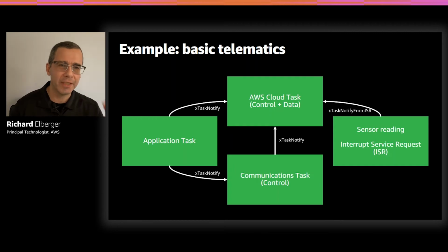But if I have an extra clock on the MCU, on the microcontroller, I'm definitely going to use it, all right? So there's no reason not to. Usually reading the data from a sensor is done over GPIO or an ADC or an I2C bus and, well, more rarely a SPI, right? This is just wrapped in a function, easy.